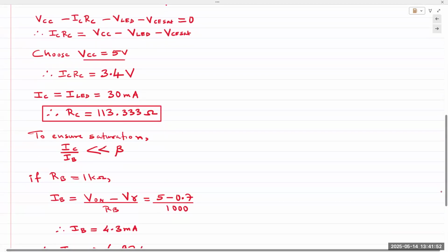Now, in this particular BJT operation, we want the reverse. We want it to stay in saturation. In the previous circuit, we wanted it to remain in the active region. Here, we want it to remain in the saturation region. We don't want it to leave saturation. Saturation means current is at a saturated constant level, right? The flat horizontal line.